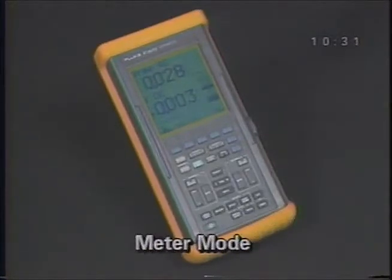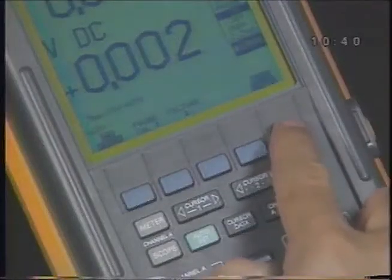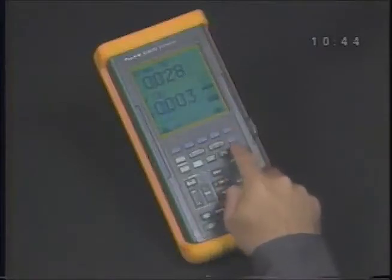Your Scopemeter should power up in meter mode after a master reset. If your room lighting makes the LCD readout difficult to see, turn the backlight on. Press the backlight soft key to toggle the backlight on and off, and the up-down arrow keys to adjust the contrast.